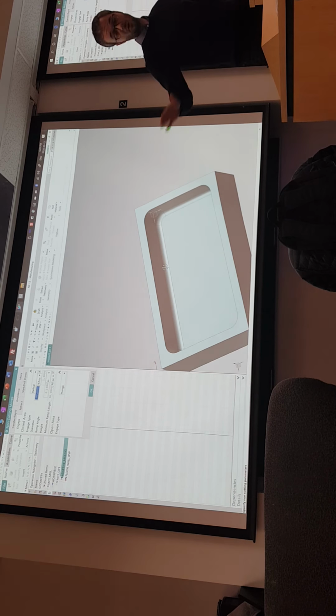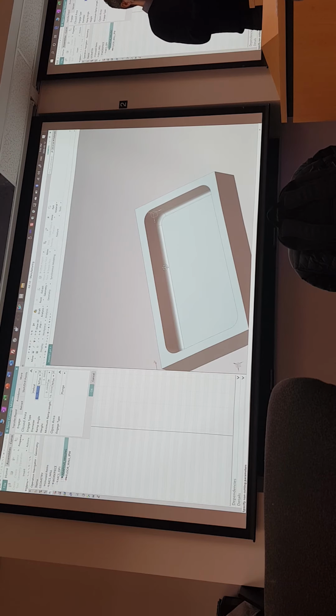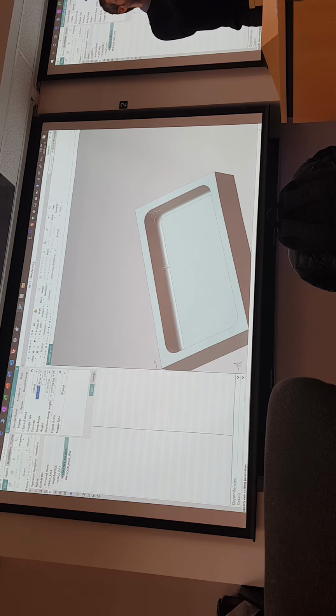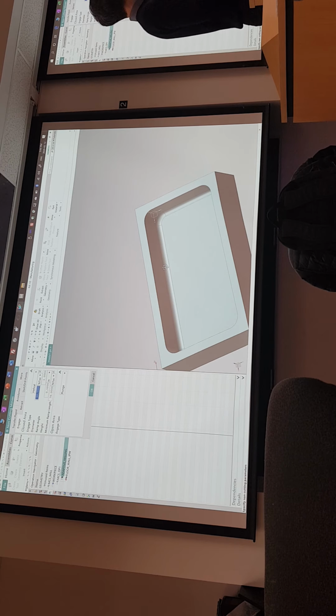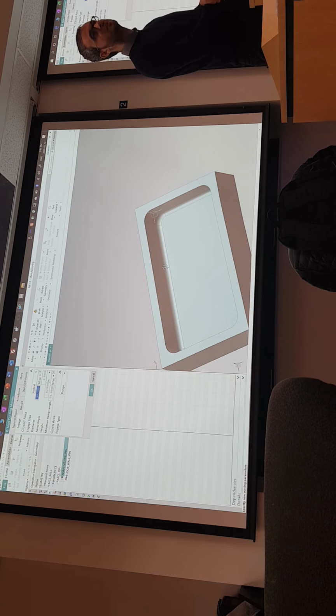The same applies for floors, like webs. Sometimes you want to leave floors, especially on large pockets, thicker, and start in the middle and work your way to the stiffeners. That way you're leaving some stock, so the material is a little bit more rigid, and you're also starting at the most flexible point while there's still stock in that pocket, and you're working your way out. If you start on the outside and work your way in, you've removed all the support from that floor and you've left it all in the middle. But for these types of parts, it's fine.